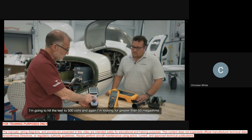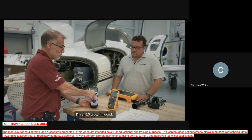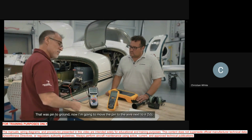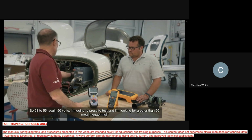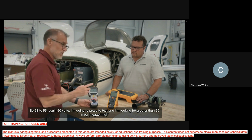I'm going to hit the test of 500 volts. And again, I'm looking for greater than 50 megaohms. I'm at 5.3 gigs. I'm good. That was pin to ground. Now I'm going to move pin to the wire next to it, 55. So 53 to 55. Again, 50 volts.